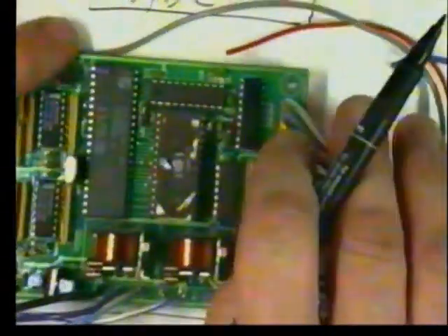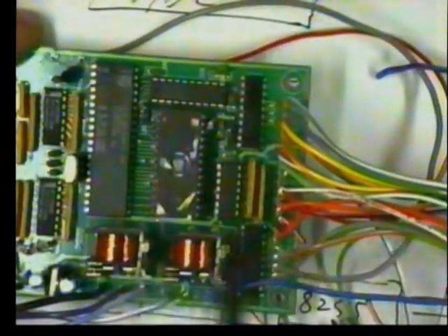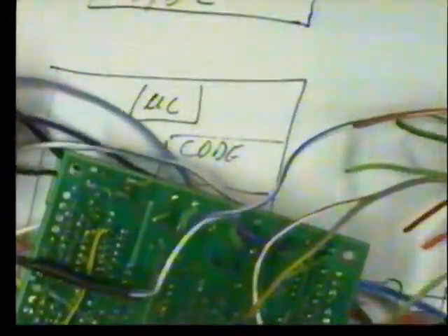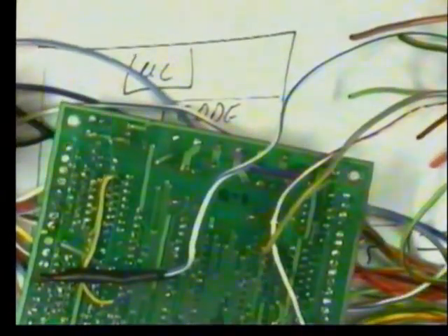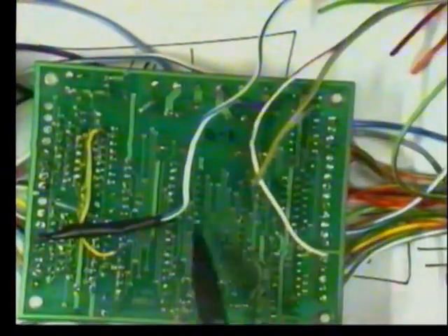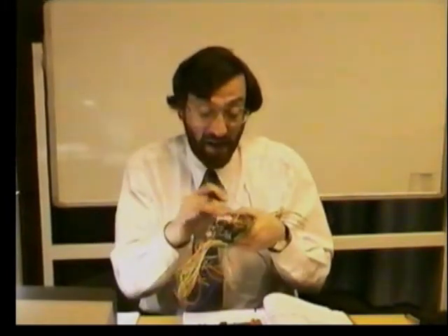Because of course, when you lay out a printed circuit board, you do the horizontal lines on one side and the vertical lines on the other, using the vias to connect the two. So here we have the fully expanded bus. What we've had to do with that is to bring out onto this computer the whole of the address and data bus. That's so we can interface these bus-orientated devices.